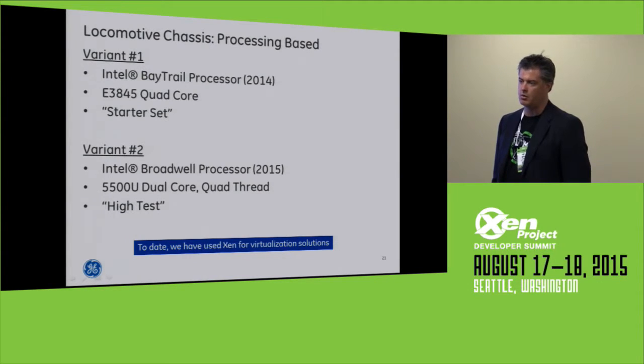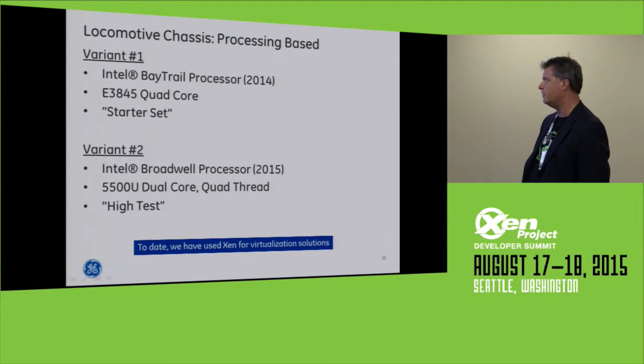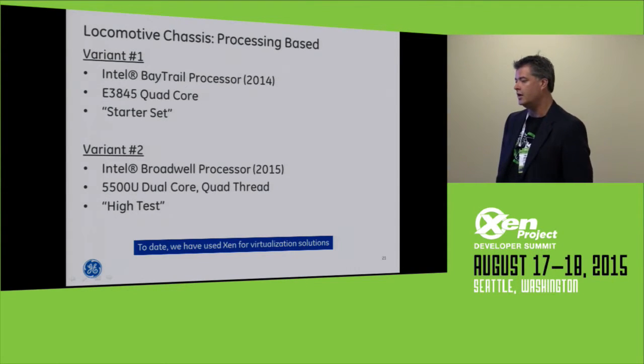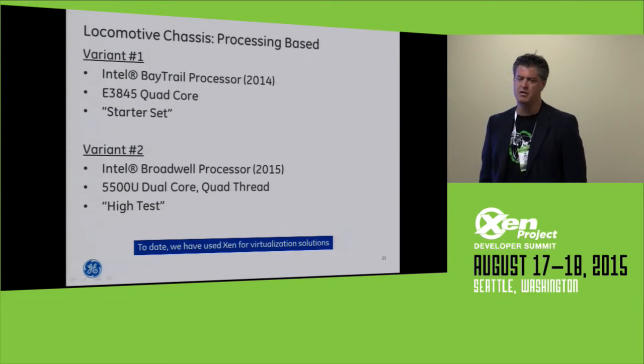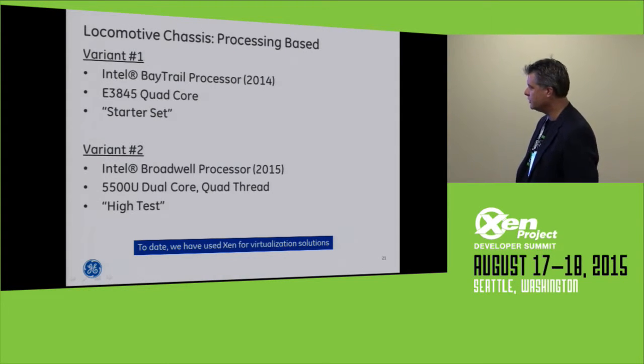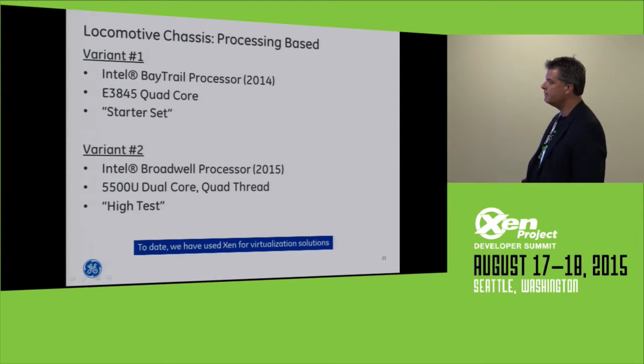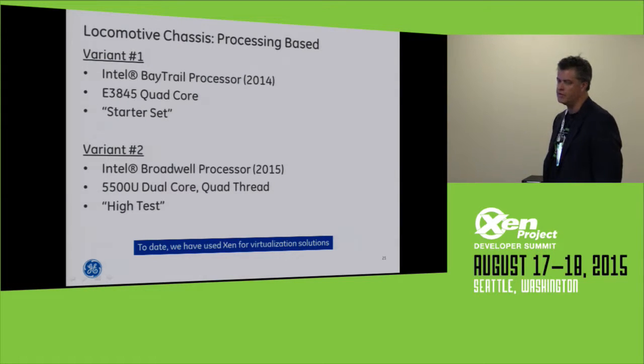It's quad-core running at 1.9 gigahertz. A lot of the virtualization extensions that that particular processor has was borrowed from the Core i5. So it's a really, really nice industrial-based junction temp of 110. Our processors, especially with no fans, we're usually running right around 92, 94C. Our RAM usually gives out long before our processor does. We call that our starter set. So if a customer comes along saying that they'd like to have an application board, that's typically the one that